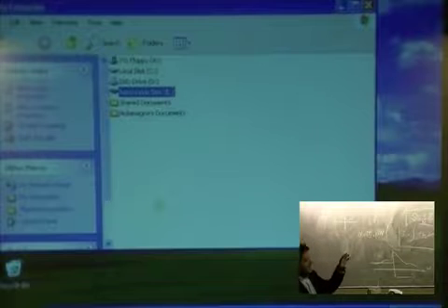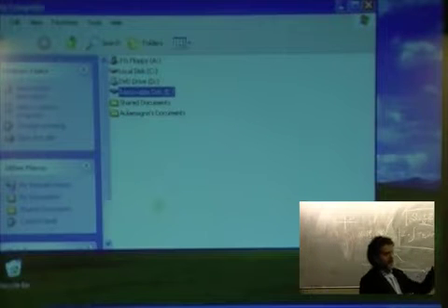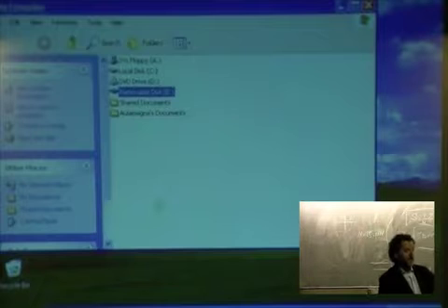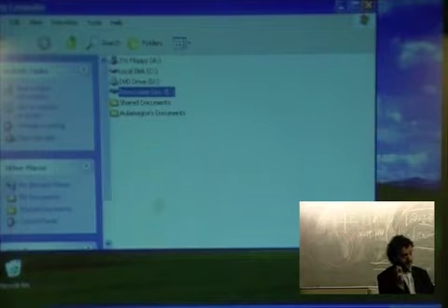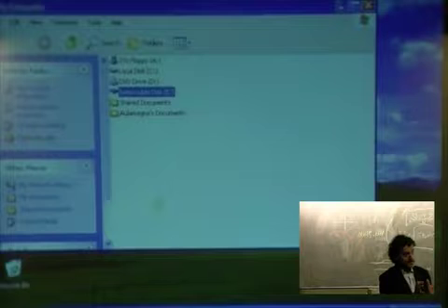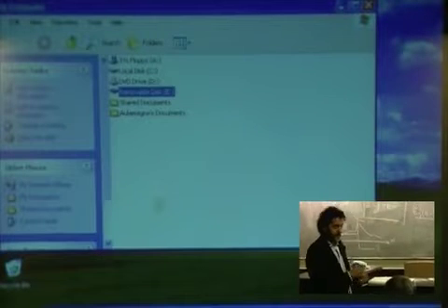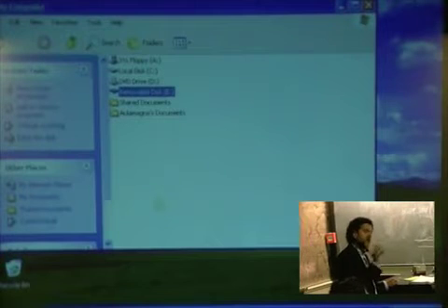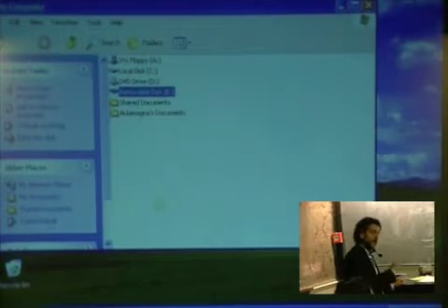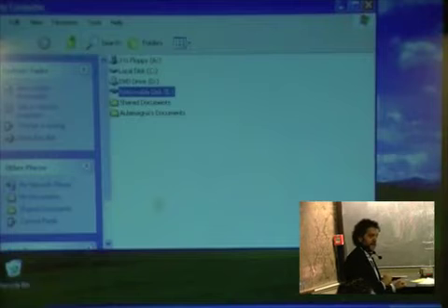At a certain point, I said there is a dissipation term and the reactive term. Generally, we neglect the reactive term. This is possible only if the total mass of the oscillators is small compared to the mass of the master. Otherwise, this effect cannot be achieved. So it is a good question. Yes, definitely, you are right. It is a condition that we have to respect in order to have this very fast energy transfer.